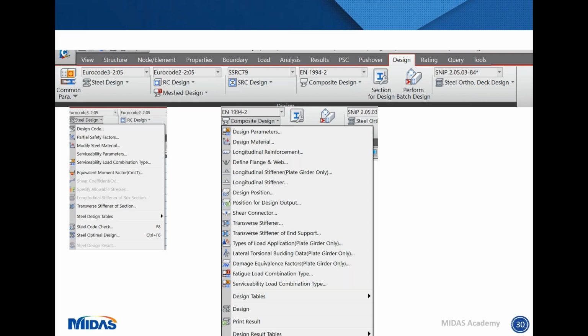As you can see here, for the steel design one, you start off with the design code and any partial safety factors that you might want to consider beyond what is defined in the Eurocodes. One of the ones that you can see as well is the one for serviceability load combination. The software should, for the most part, pick up from the previous slide the combinations which are for SLS. But because it's Eurocodes specific, particularly when you're doing concrete design, you might need to distinguish between a characteristic combination, a frequent combination or quasi-permanent. So there's the function to do that within the software.